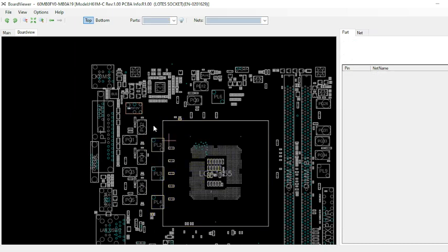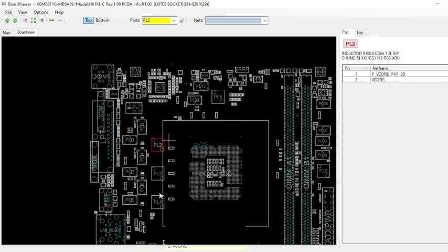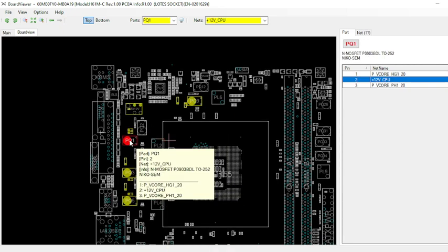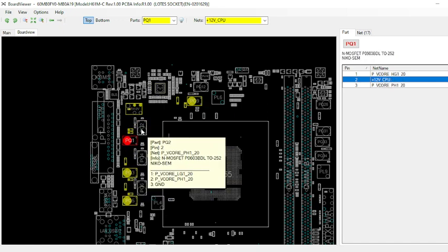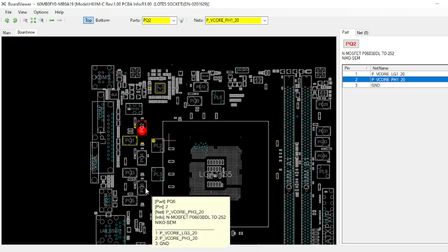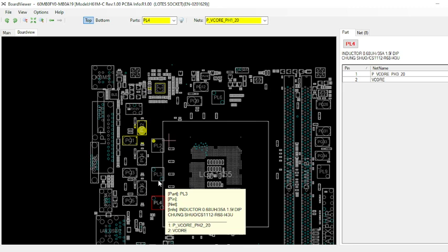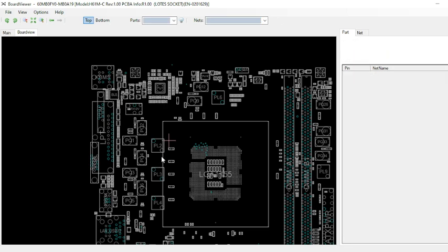It means we have some sort of shorting in the VRM section. In this section we have three coils, which means we have a three-phase power supply, and we have to check which MOSFETs are shorted. Just remove that pair, meaning you have to remove these two MOSFETs. Two MOSFETs will be generating Vcore, and at least one pair, or two pairs, should be there generating our Vcore supply. This is the main thing you need to know about the VRM section.